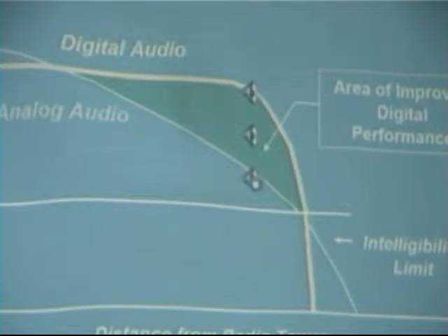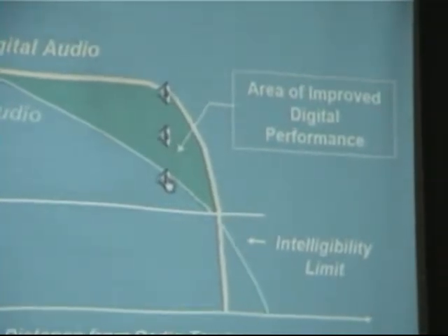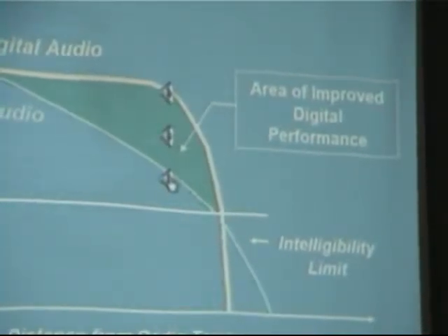What we did here is we concatenated three tests. The first test is just a stationary user with a weak signal. And then we have a moving user, first with what we call a fast fade. In the industry, the standards for Motorola type radios specify testing at the equivalent of 100 kilometers per hour for a fast fade and 8 kilometers per hour for a slow fade. And you've all heard the fast fade is a picket fencing thing, and a slow fade is a